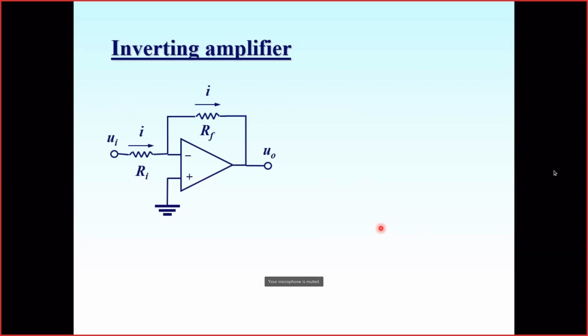Why will they be the same? Because if they become different, the output changes immediately. They are not the same just because we want it. They are the same because the operational amplifier itself, via this feedback, controls the voltage on the feedback input in such a manner that it always will be equal to the second input voltage. It's not just a declaration.